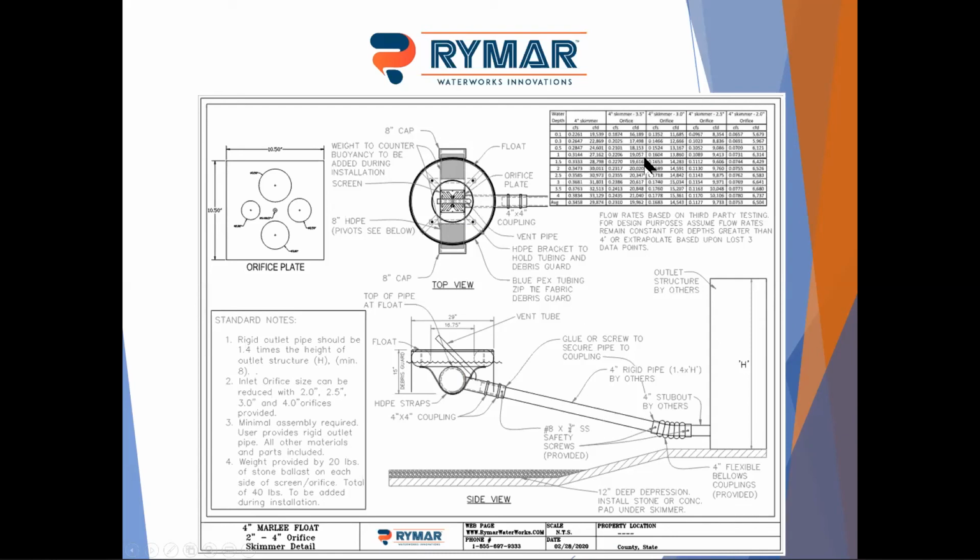Again, all of our details include the flow rates. And each of our skimmers have what we call an orifice plate. I'll show you a picture in just a second, but each of these plates has different orifice sizes. So every one of these skimmers that we make will have anywhere from 3 to 5 different configurations, so it has a wide range of flow in each one.